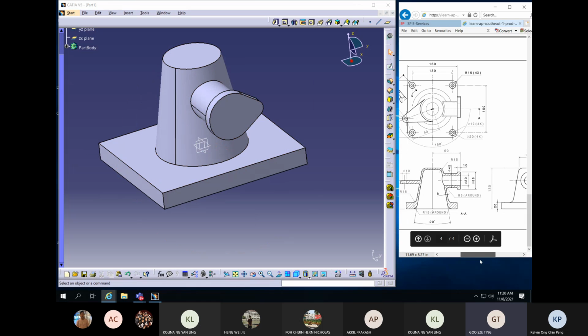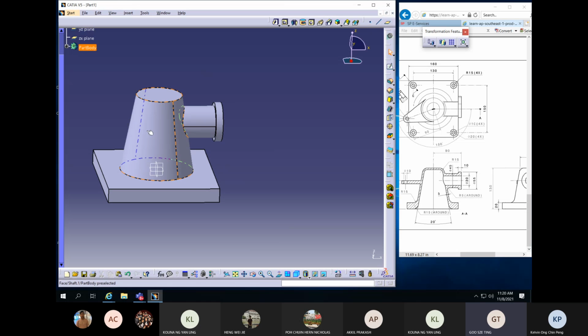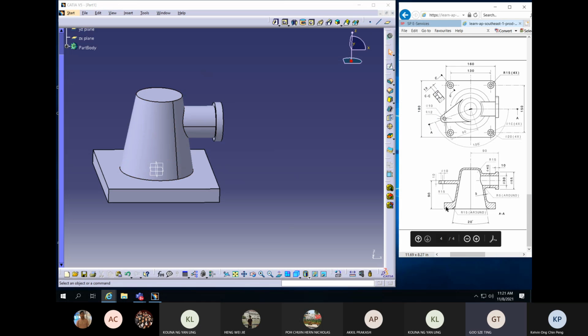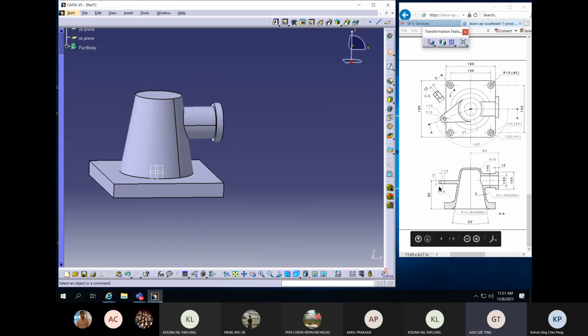All right, so now what's left is the internal cutout, right? What I do is I cut out this guy here first, then I cut out this guy. So later then do this part. Okay, so now I do this part here. The easiest way to draw this part is to draw a plane at this point and then draw the exact shape. So what do I need to draw the plane? My plane is here, right? So the plane from here going upwards is 90.